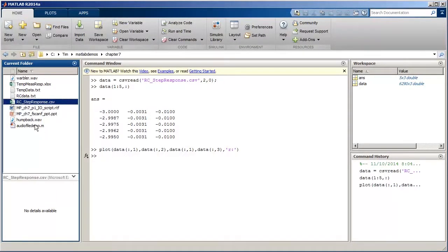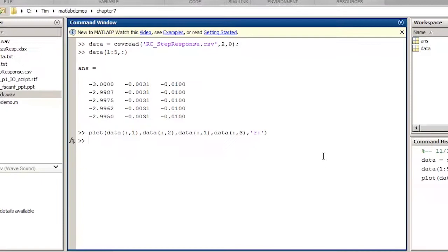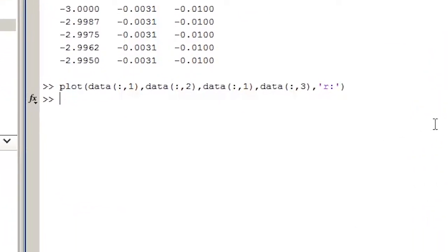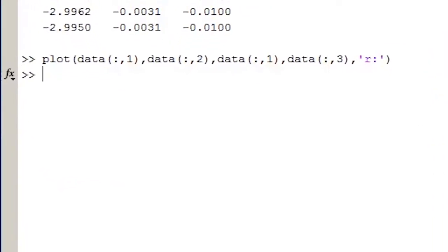The signal I'm going to modulate the whale song with is a sinusoid. This will result in the song fading in and out with time. The humpback whale song is in my current working directory in the file named humpback.wav. I'll load the song by typing the output arguments in square brackets.